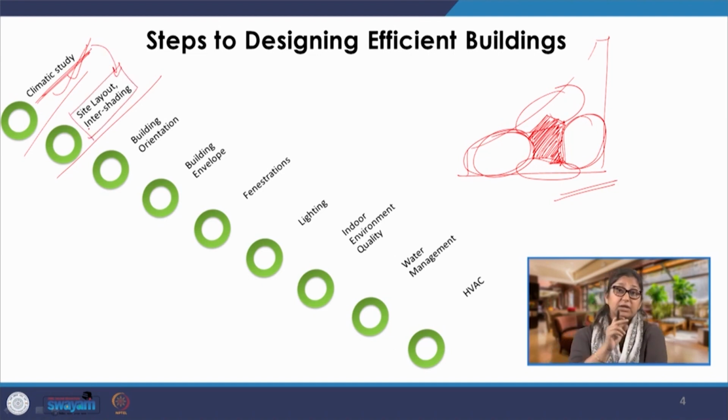In addition to energy, at this level itself, at the second step itself, we also need to take into account the drainage, which is primary. Unfortunately, we have stopped looking at drainage as part of the larger region. We think that my problem is just this site. So, I will have, okay, my site is like an airtight container, and the water outside my boundary is not my problem.